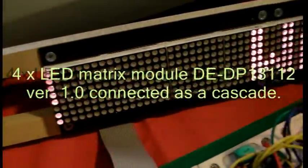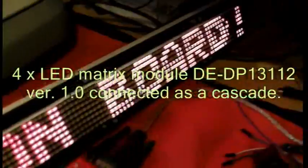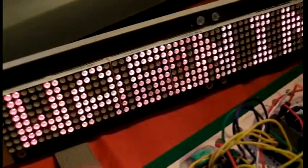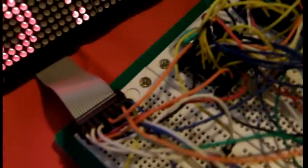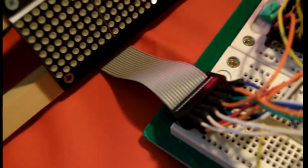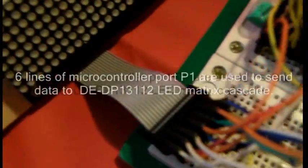And for the presentation board, here is the LED Matrix board, which actually consists of 4 modules connected as a cascade serially. These are intelligent modules. Each of them has their own controller and memory, and you send data to them using a serial connection. Actually not the RS standard, but its own proprietary serial line.